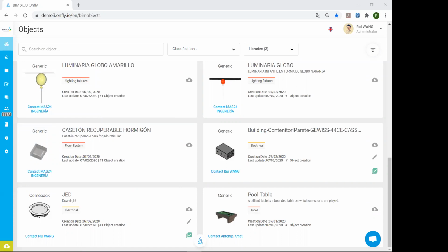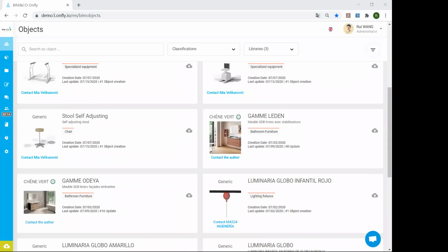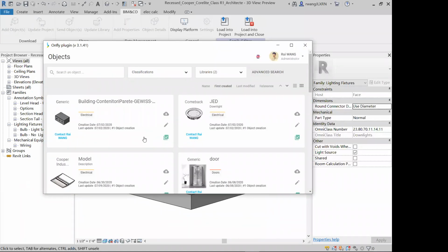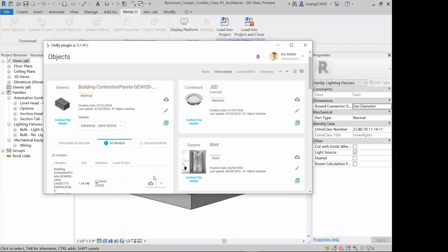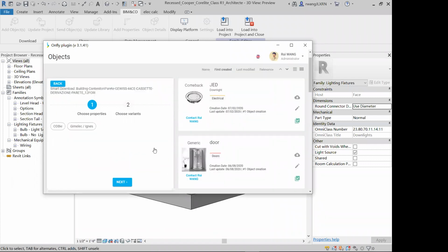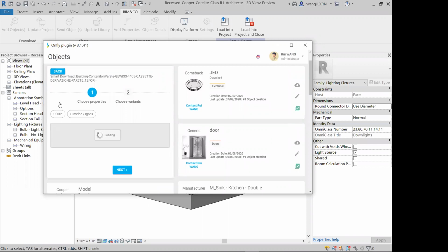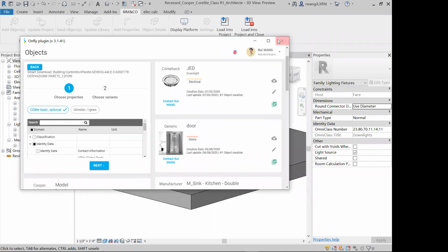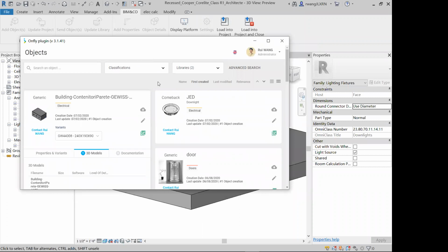Yes. Does the library already have a list of standard properties like Uniclass, Cobie? Yes. That's another good question. When you decide, for example, to download your parameter into your model, you click download. Okay. Here, for example, from the plugin, I download the data. Once from the download, in step 2, you can define that you will follow the Cobie standard for all the parameters. If you click Cobie, all your parameters will be named or grouped by the Cobie standard. Of course, we also have Omniclass and Uniclass already in the library. I can show you.